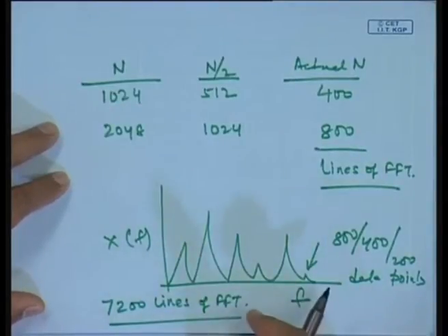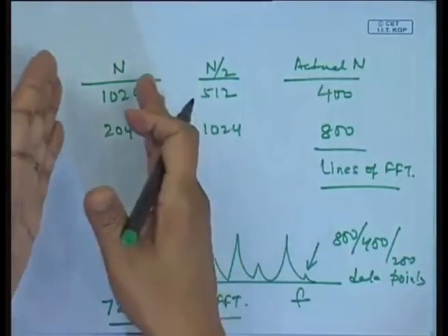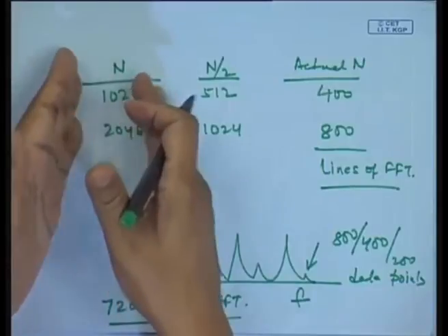This means 2048 data points in a block are taken, the FFT analysis done, and the results displayed. Nowadays, for FFT analyzers, I can either do it through software given by that equation, or even implement it in hardware where all these computations are done.